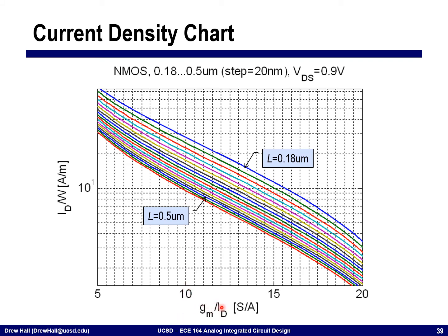The other thing that you can see is that for sub-threshold, when we start to get up to gm over ID of 15 to 20 and even a little bit beyond, I have to make the devices very large in order to have the same amount of current pass through the devices. And so the width and the length of the devices for sub-threshold grow quite dramatically.